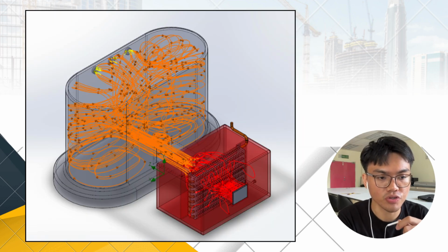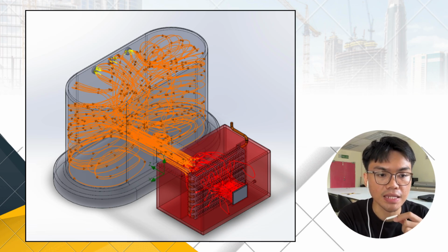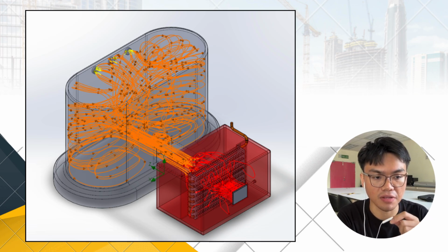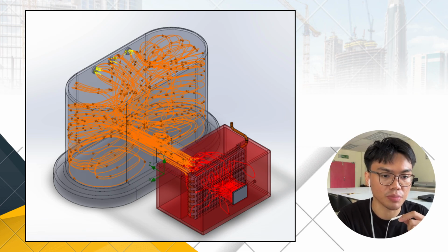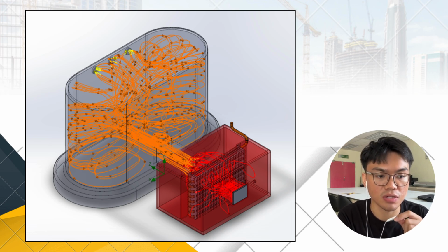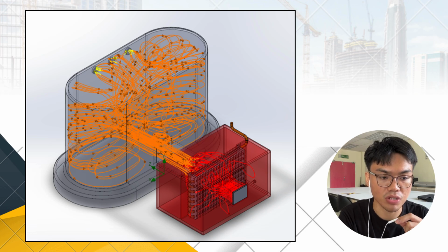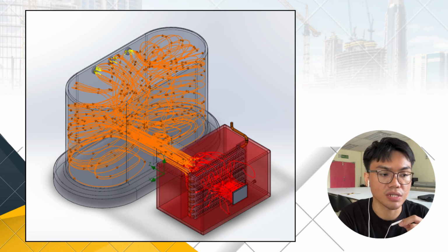These are the flow trajectories from the heat exchanger housing into the drying chamber. The heated air first passes through the radiator fins, and then it enters the drying chamber through the connecting duct. Once inside the chamber, the airflow forms a large circulating pattern instead of moving directly to the outlet, which is very useful as heat is distributed more evenly throughout the chamber, supporting the average temperature of around 69.6 degrees Celsius uniformly across the drying chamber.